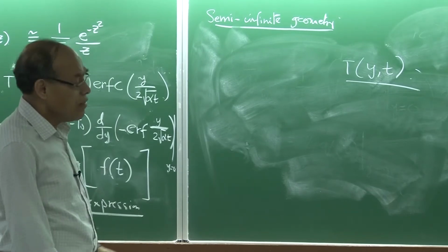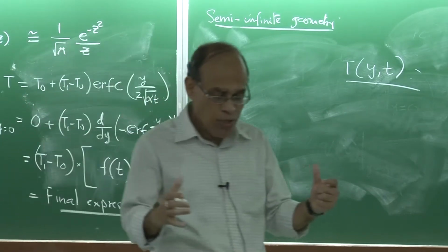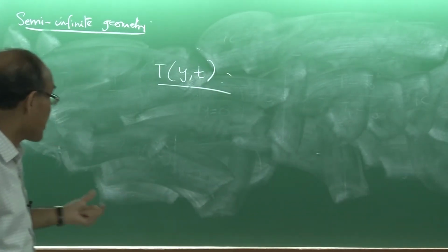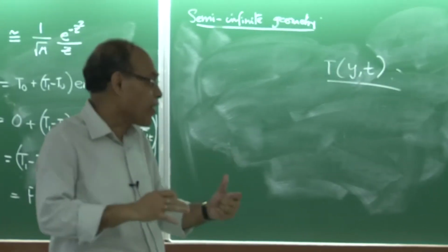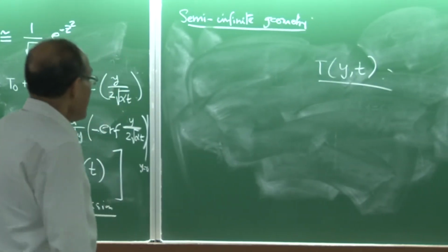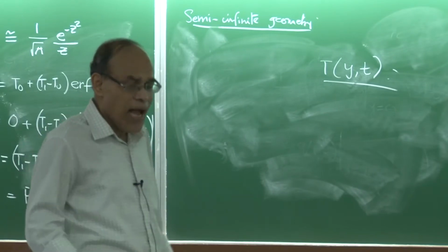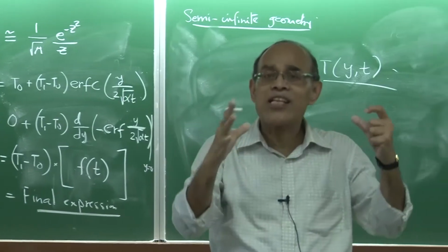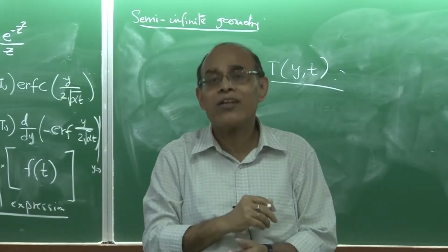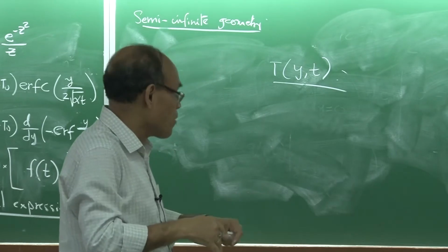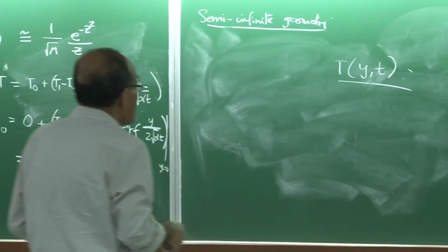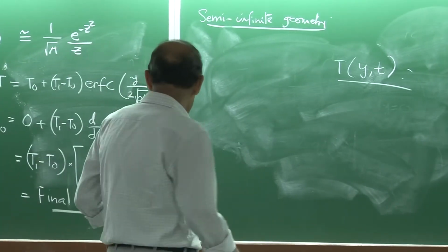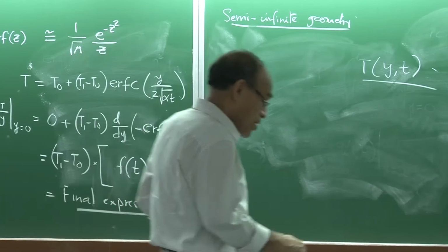Similarly, as I have shown, we have the infinite series solutions, and I have been saying repeatedly that computing the infinite series is going to be very, very difficult. So, in the context of slab geometry, and not just slab geometry, but an infinitely long cylinder as well as a sphere which exhibits 1D heat conduction, because of its theta and phi symmetry, we do not have to do a summation solution every time.